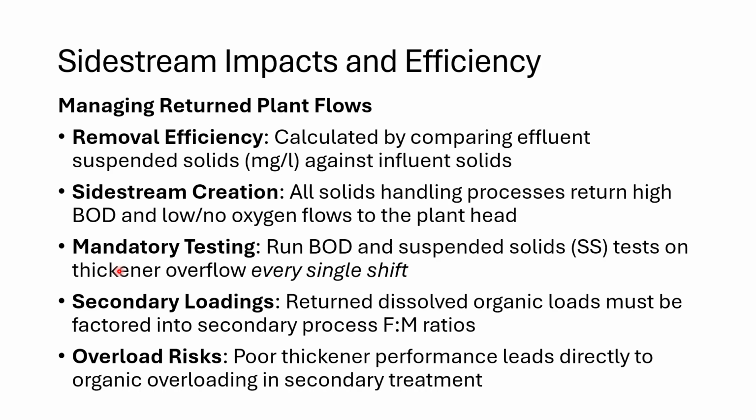Okay. So solids handling processes return, if there's a side stream or return flow, it's going to have a high BOD, biochemical oxygen demand coming in, and low or no oxygen coming to the plant head. So you get a double whammy. You get basically a bigger food source for your microbes, and you also get less oxygen coming in. So those are two things you have to deal with.